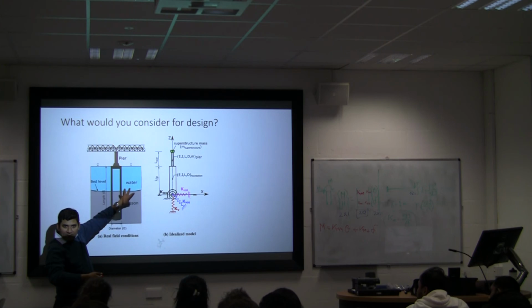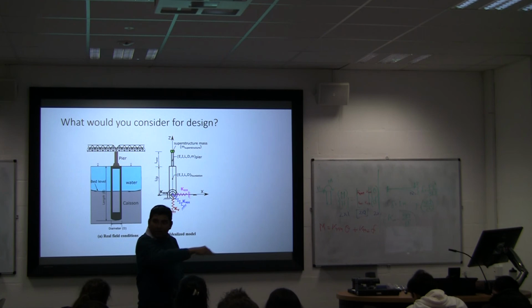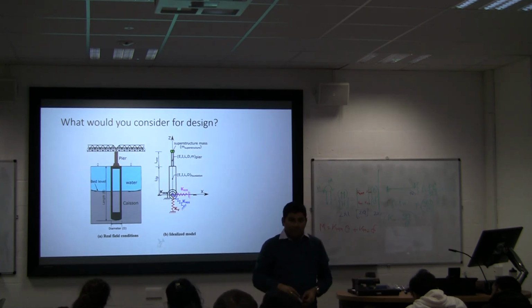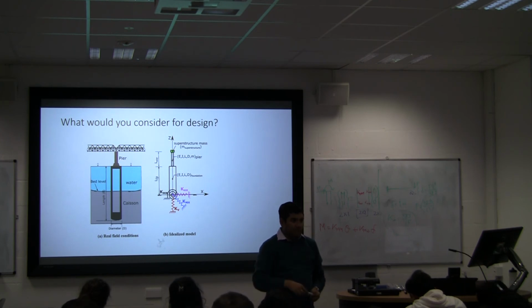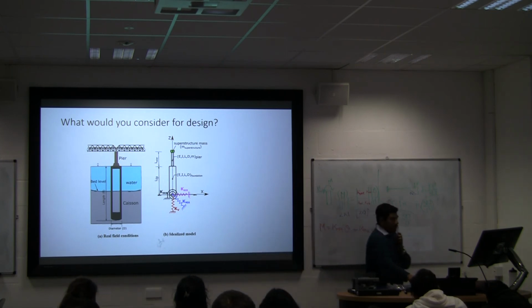There will be large movement, isn't it? Because you have a load on one side. Then you must check under that condition how much it will deform. So you have to think about all these steps, how you will construct the whole bridge. Okay, so this is one.